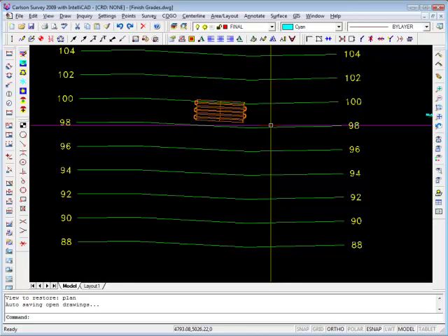We're going to assume that the bottom of that highest row, the invert of that highest row, is at grade, meaning it will be at 100. The finished grade over the field is 2 feet higher because we have the tube, which is 12 inches thick, and 6 inches of sand, and then another 6 inches of loam to bring us to the finished grade of 102.